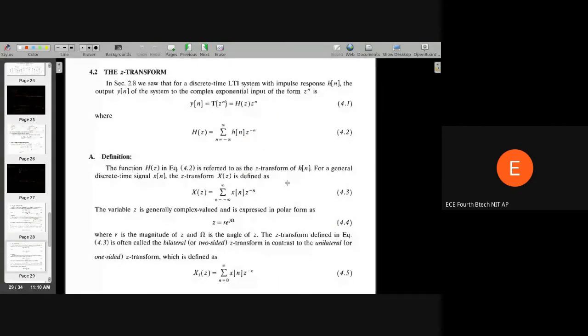In the same way, Z transform is the inner product between your signal h[n] and a complex sinusoid, but depending on the value of r, it will be increasing or decreasing. So this is the basic idea behind why we use Z and Laplace transform.